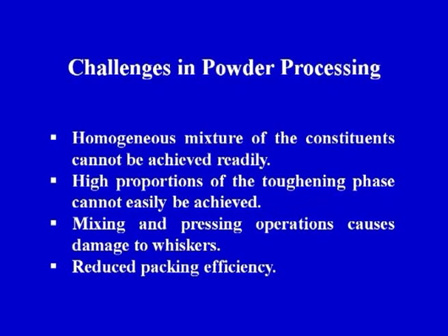Next challenge: mixing and pressing operations cause damage to the whiskers. In the specific case where the reinforcement is in the form of whiskers, it has been noted that the mixing and pressing operation sometimes causes damage to the whiskers, and when the whiskers are damaged, it would certainly affect the mechanical properties of the product processed with whiskers as the reinforcement.